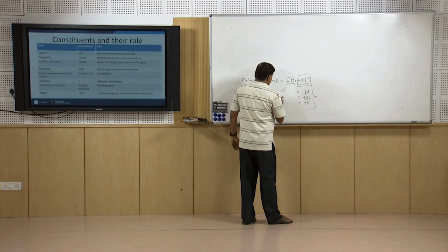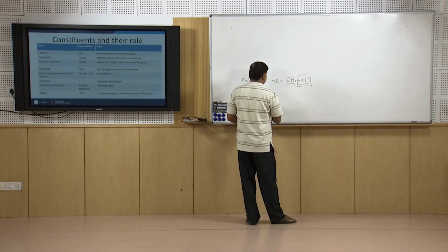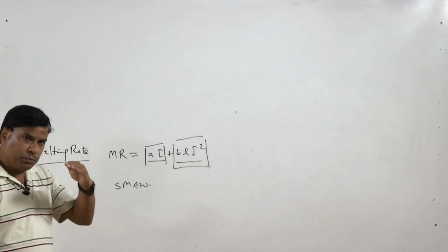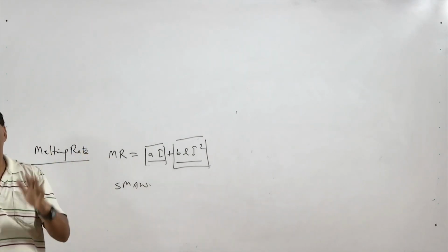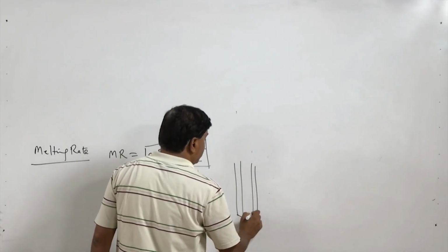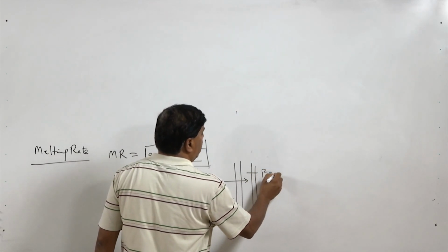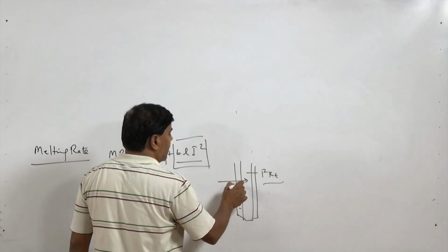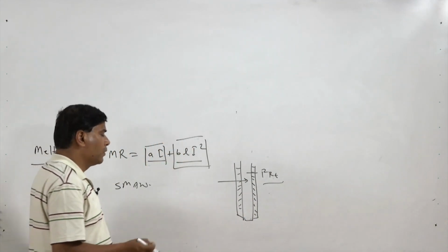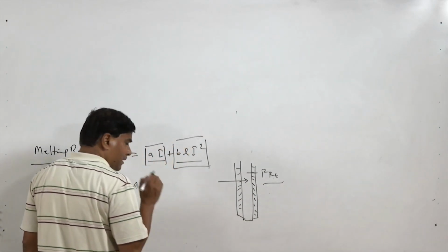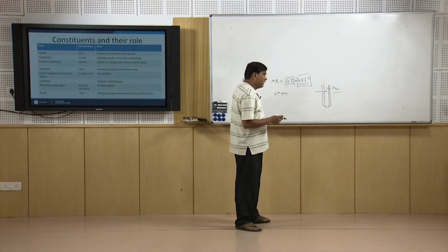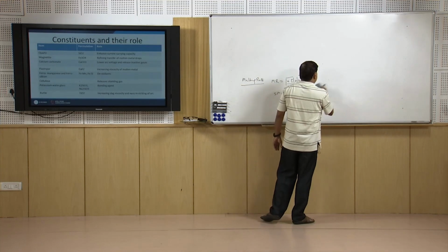For example, in the case of the shielded metal arc welding process, the higher level of current is limited by the current value at which thermal decomposition of the coating starts due to the flow of current. Say this is the electrode and this is the coating. If you keep on increasing the current value, then high I square R heating of the core wire can start damaging the coating much earlier than it should. Because of this we will not get the benefit of the coating over the core wire in the case of SMAW, while in the case of tungsten inert gas welding it will damage the electrode due to the excessive I square R heating. So, electrode life is reduced if excessive current is used.